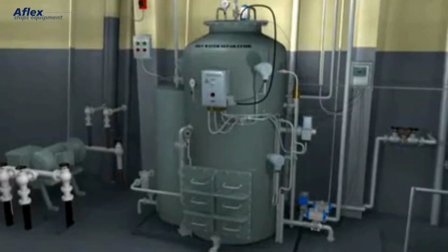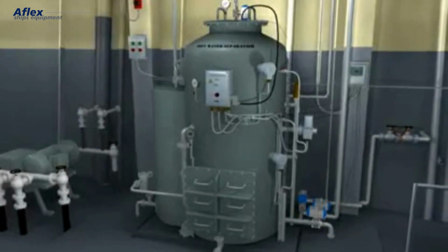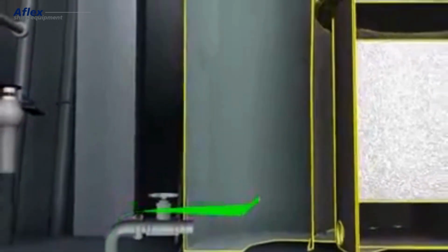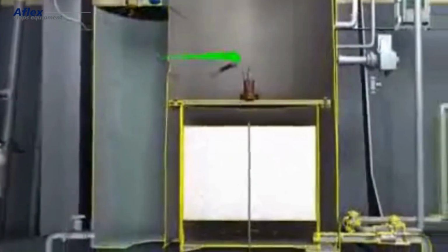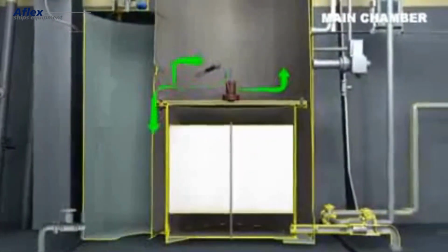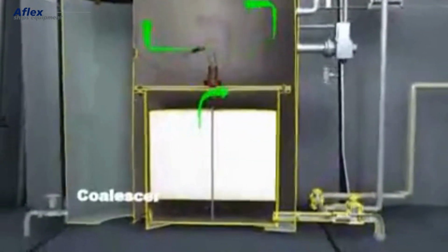Let us now look into the operations and functions of an oily water separator. This is the path that the oily water takes from the bilge pump discharge to the overboard valve. The function of an oily water separator on board vessels is to separate the maximum amount of oil particles from the water to be discharged overboard from the engine room or cargo hold bilges, oil tanks and oil-contaminated spaces.